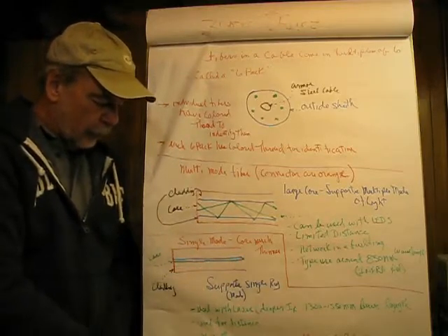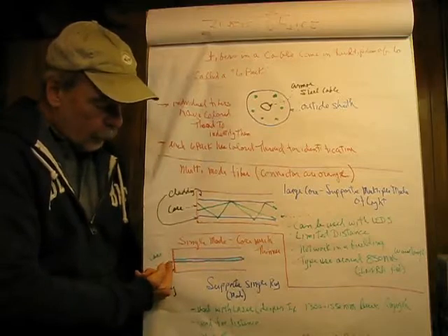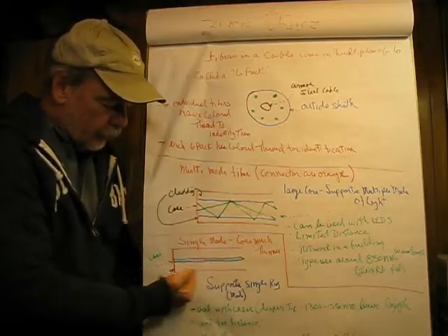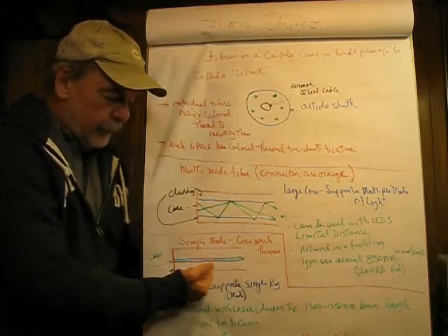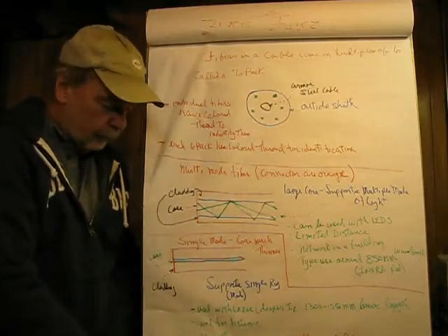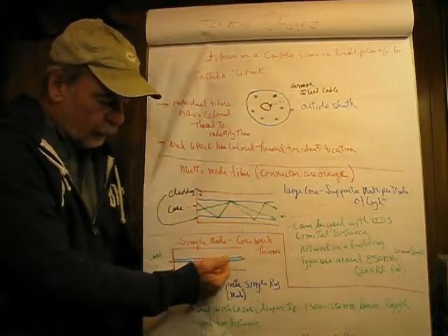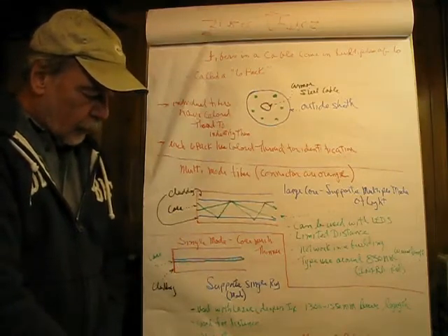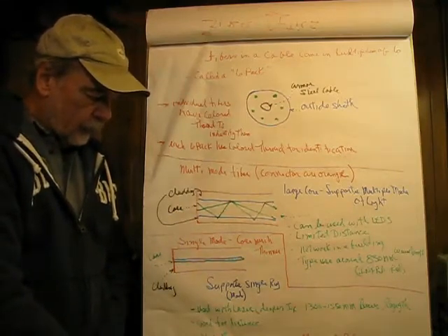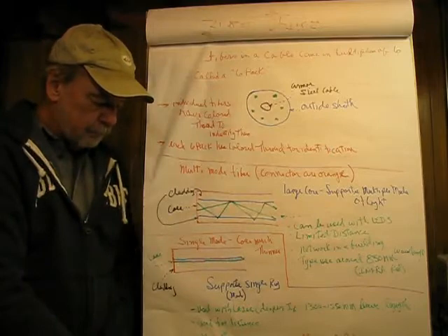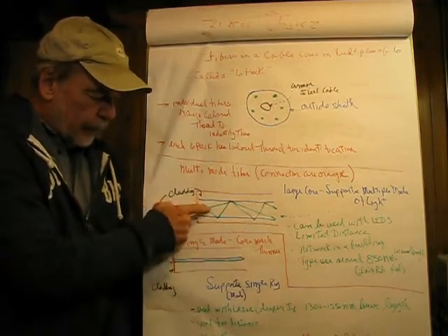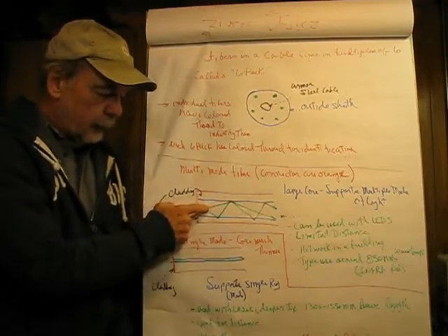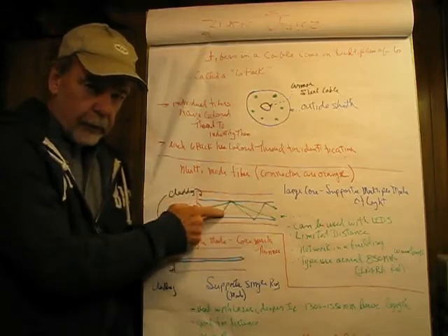and it only supports one mode. That is, a ray travels down the center of it, and it is also following total internal reflection. I haven't shown any in here because it's so small. So single mode fibers are good for long distance, because we don't have the issue of pulse spreading, which we'll see in a minute here.